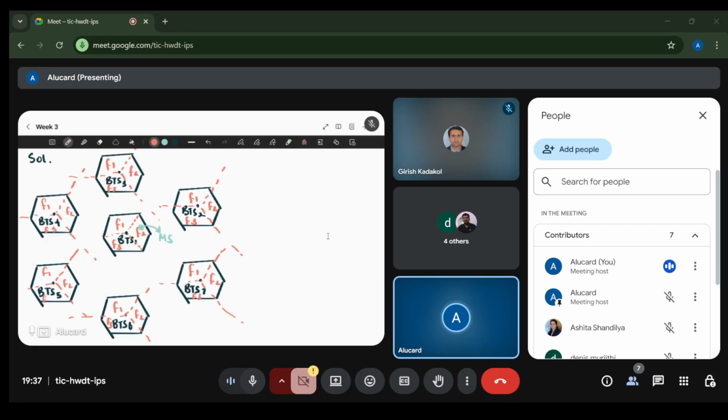Now this mobile station who is sitting here is receiving the transmissions from his own base station in the frequency band F2. Consider the transmission from base station 2, which is coming in this direction towards the mobile station. That transmission is actually happening in the frequency band F3. So there is no interference because F2 and F3 are orthogonal.